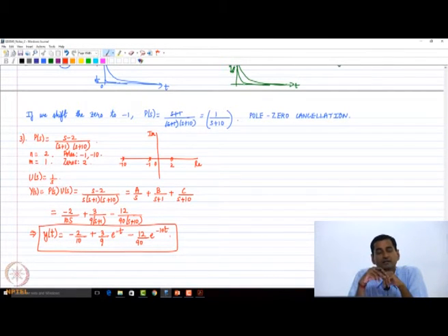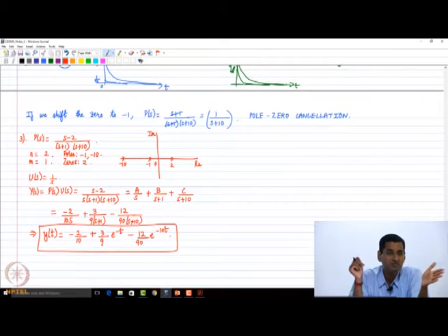Okay. So any other observation here that you can make? I'd like to ask, does the closeness to the other pole matter? It matters, right? So if you move the 0 closer to -10, the effect of that pole will go down drastically, right? Even without a 0 near to it, its effect is anyway small.